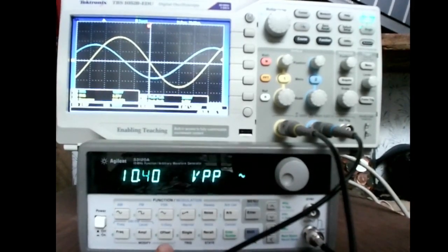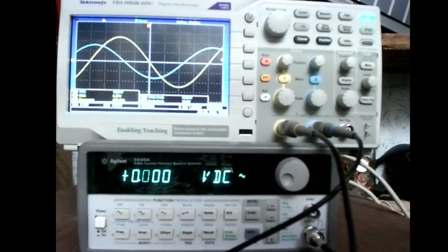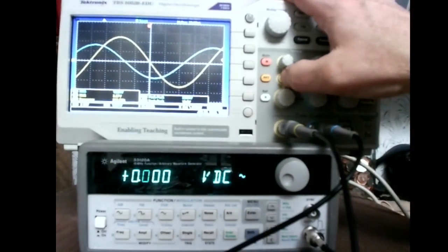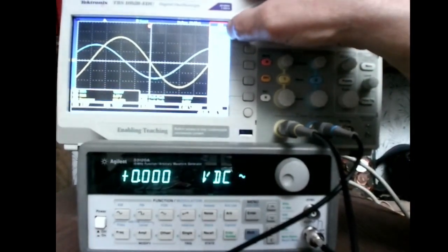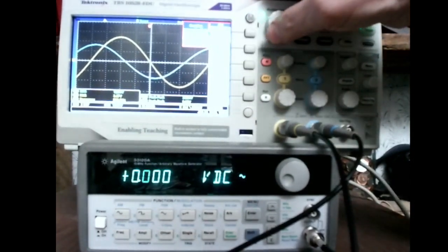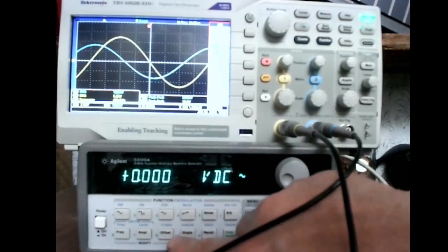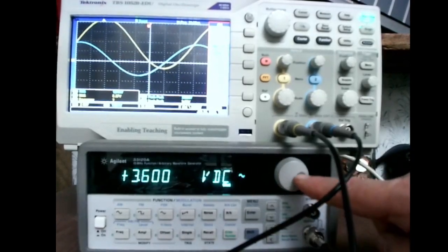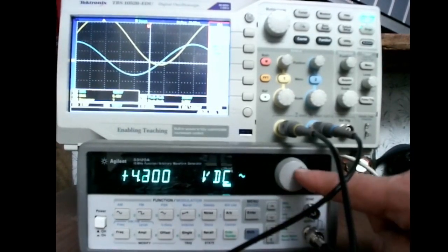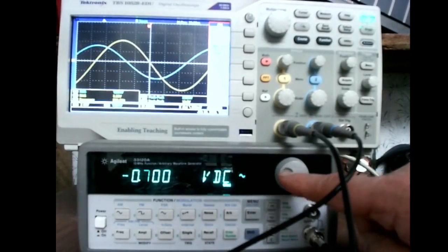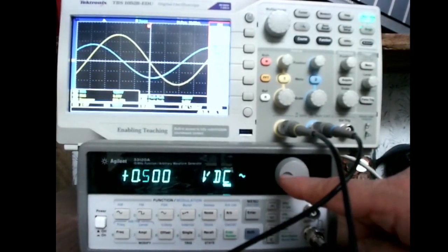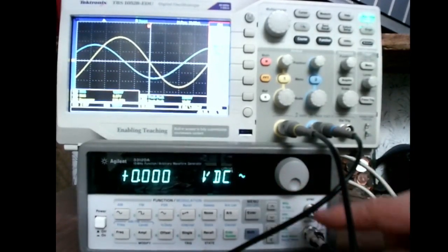Now we can also add some DC. So if we do DC offset, I can press the DC. Right now I have 0 DC offset. Okay. If I go to channel 1, remember I talked about AC coupling. I'm going to flip over to DC coupling. And now I'm going to dial up my DC. And what you see is that yellow waveform going up and up and up. And now I'm dialing it back down, and I can actually dial it negative. So the yellow waveform is going up and down. All right. And so that is DC coupling.